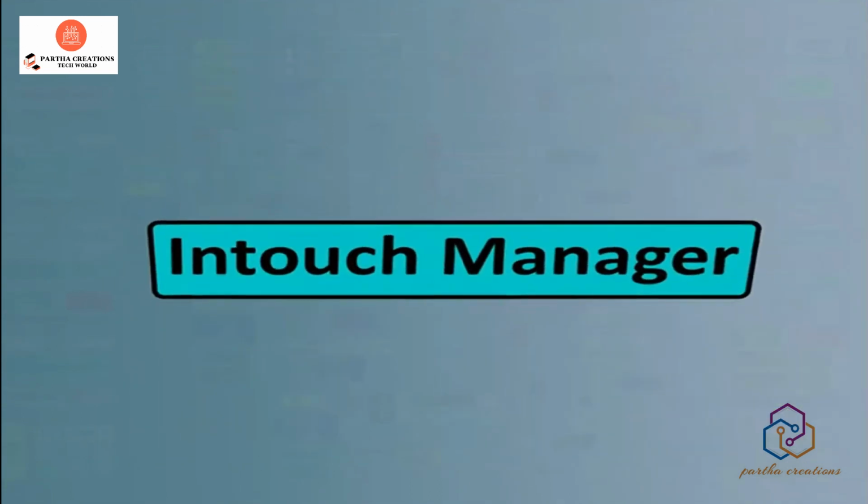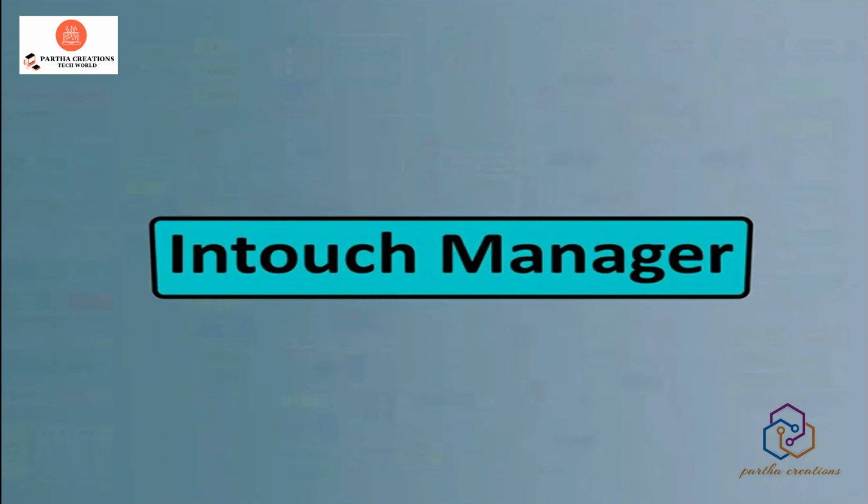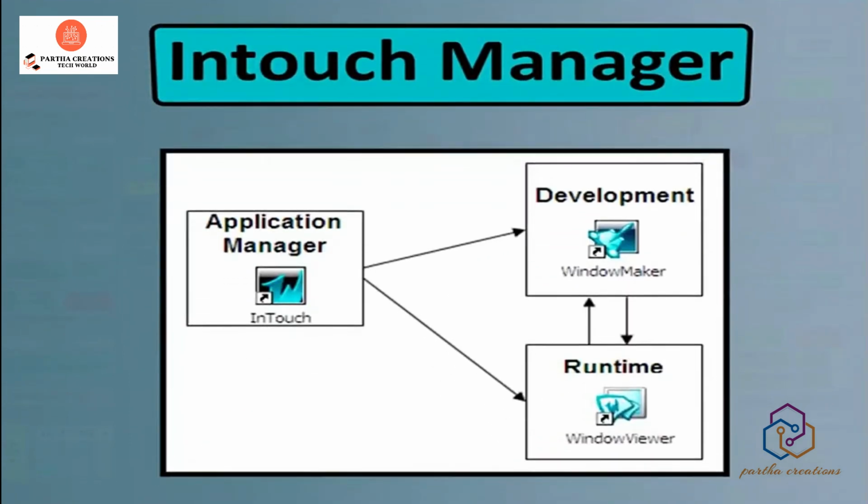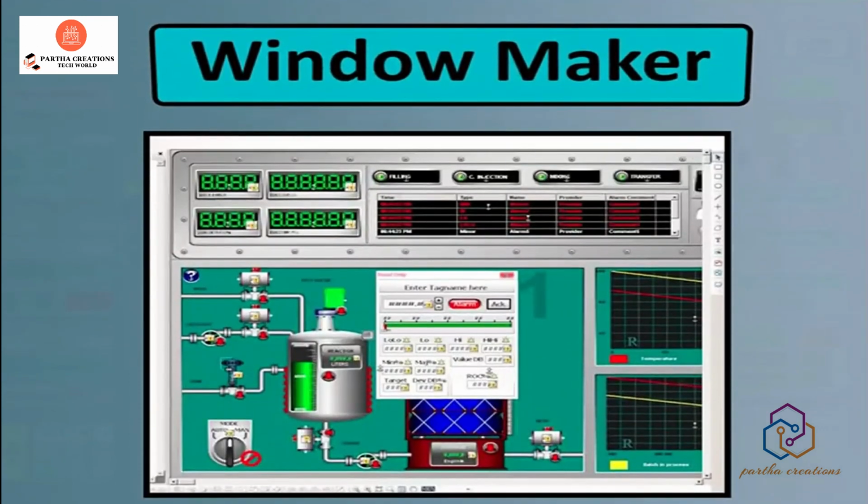In the InTouch Manager, when you open the software, you will be able to see two windows. Which ones? The first one is window viewer, which is also called runtime environment. And the second one is window maker, which is called development environment. In the window maker, we will be developing all the animations of the plant in SCADA. It can be called development environment or development window or window maker. You can call it any of these things.